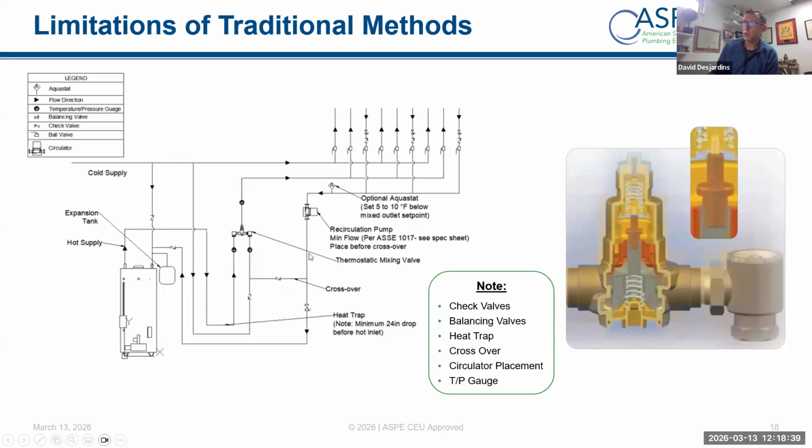So this recirc pump takes the recirc flow, and we put some of that colder water into the cold, and the rest goes back to the water heater and gets pushed out into the hot side. That's really how it's going to operate. Now, there's a balancing valve here, and what that does is force most of the return water back to the cold side.